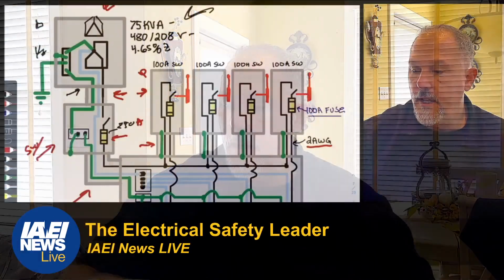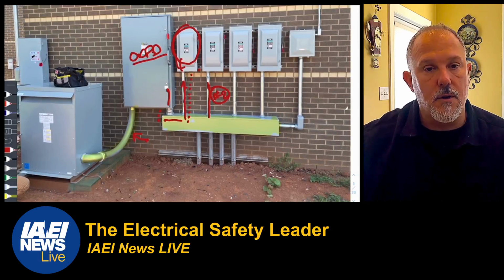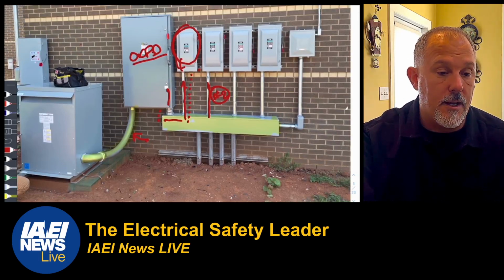And then finally, for field installations, if the tap conductors leave the enclosure or vault in which the tap is made, the ampacity of the tap conductors is not less than 1/10 of the rating of the overcurrent device protecting the feeder conductors. Now, for field installations, if the tap conductors leave the enclosure, you have to look at this application and say, do we leave the enclosure, right? And I could make an argument that we do not leave the enclosure. If you look at everything, the tap conductors are all enclosed, so I would make an argument that we're not leaving the enclosure.